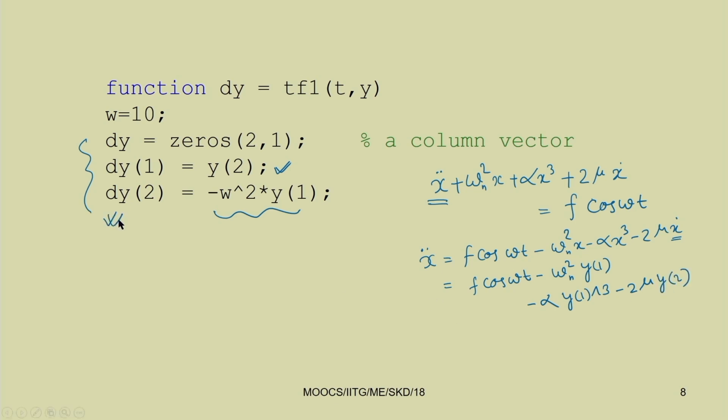So, this function 2 can be written dy2 can be replaced by this one, and you can use this same ODE45 function to find the different solution for a Duffing equation. So, you can verify for different values of coefficients, the response sometimes will be periodic.